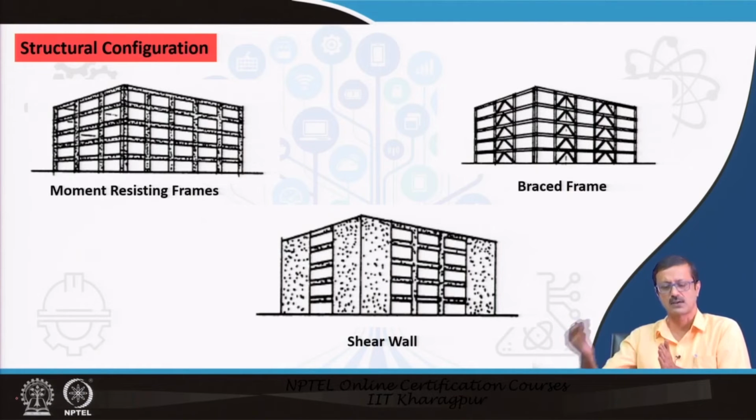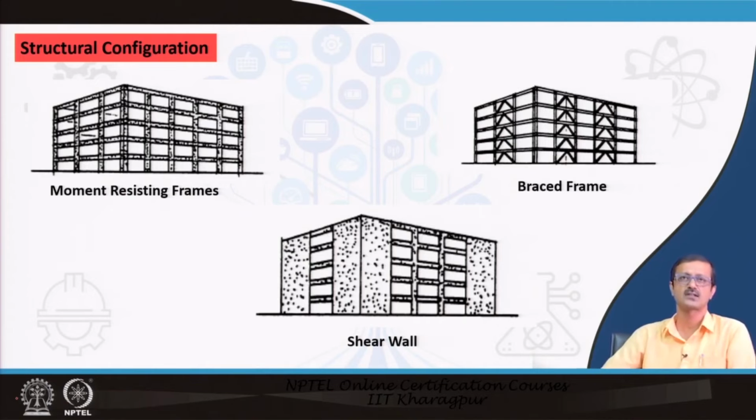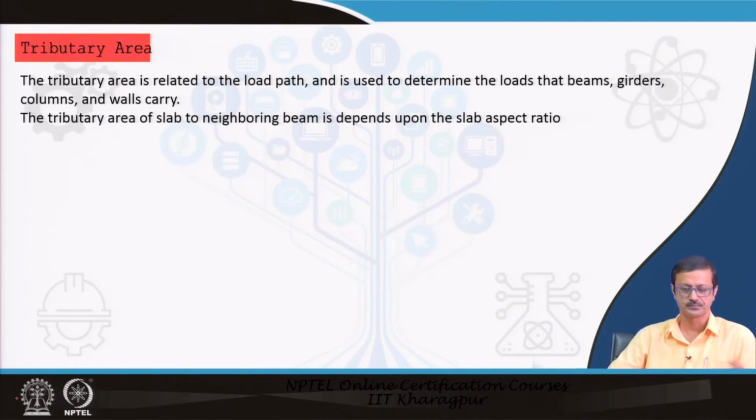We will discuss that in the last lectures of this course; two lectures will be dedicated to it. We put the shear wall in strategic locations to counter the huge shear created by lateral load, wind or earthquake. So, different configurations are possible with different structural systems like moment resisting frames, shear walls, bracings and all.